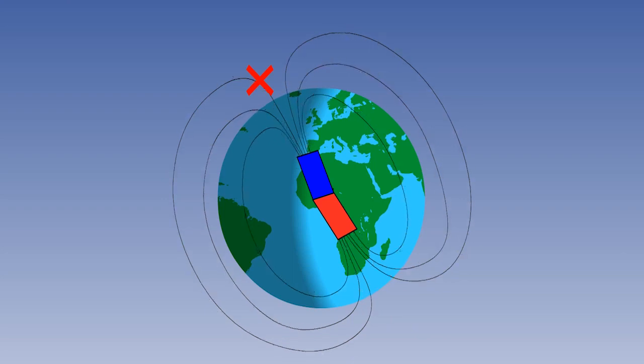Flying in parts of northern Canada would probably give a problem. But flying in northern Europe or Russia probably would not, because these areas are a greater distance from the North Magnetic Pole. So it may be possible, under some circumstances, to steer by magnetic compass even when using grid technique.